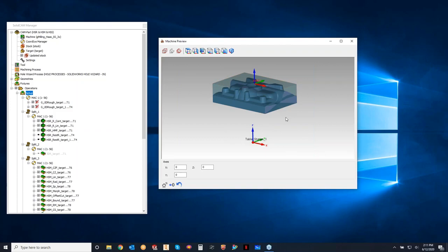No, it's a really good option. As soon as we introduced it, I didn't hear anybody say that no one's going to use this, because this is definitely something that would be highly useful to pretty much every shop I've been in. It's not because someone says, what is Mark thinking, but because it's usually that helpful. Maybe the material is a little harder or a little softer than you imagine, because even though we plug in things like ultimate tensile strength for our iMachining, sometimes you have to regulate that machining level or change your material definition to that machinability factor that we once talked about. So that sort of thing would come into play as well.